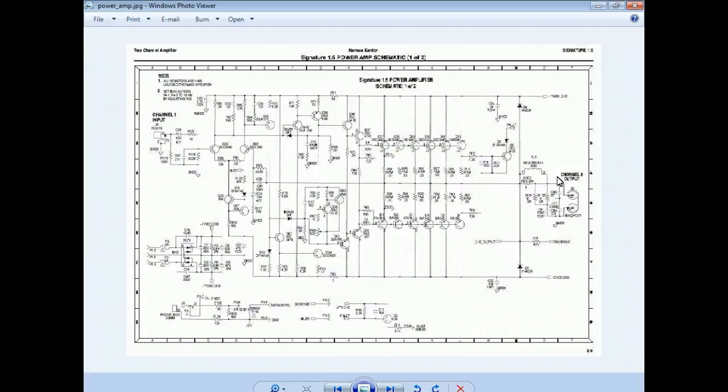Okay. So I don't know if you've ever looked at a power amp, but the leads coming from your battery to your power amp are extremely big because it's trying to deliver all that power at a low voltage. Right? You understand? So when it comes into the power amp, it goes to an inverter that turns DC into what? AC at a lot higher voltage. Usually it's plus or minus, and then it's AC. Then I can generate a negative DC and a positive DC. Right? Usually it's around 80 volts.